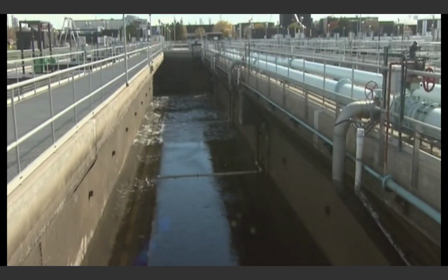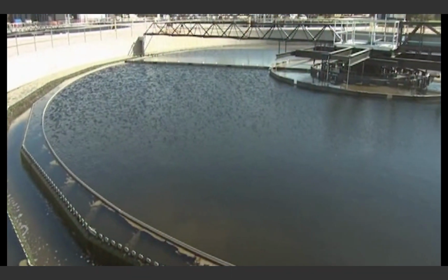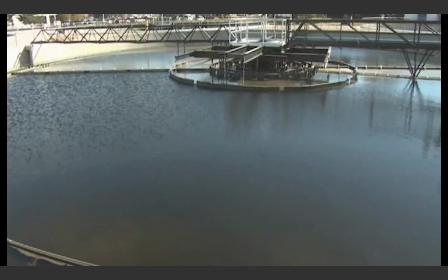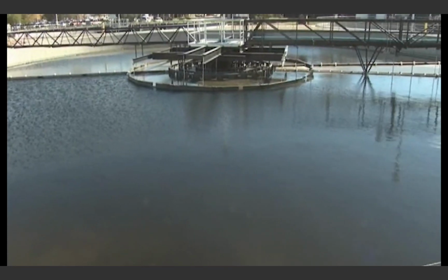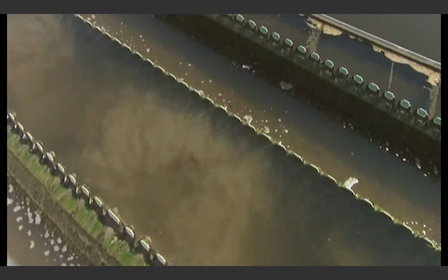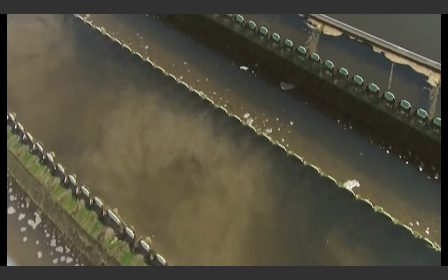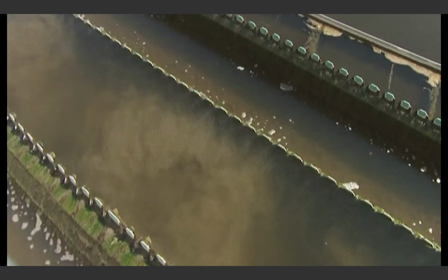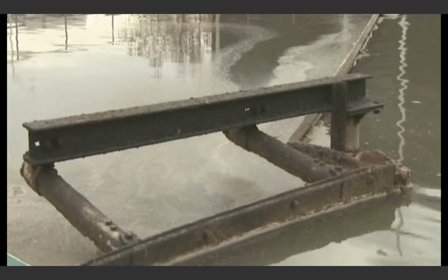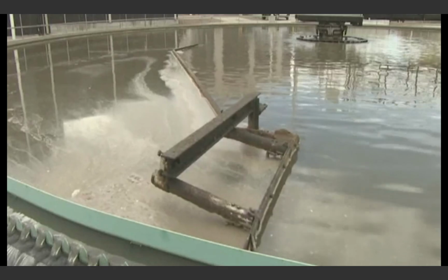As the flow passes out of the grit chamber, it goes on to primary treatment. Primary treatment involves a more advanced settling basin called a sedimentation tank or clarifier. Here, the wastewater flow is slowed down considerably, from minutes to hours, in order to settle and remove the smaller solids and skim off oil, grease, and other floatables that were not removed in the grit chambers.